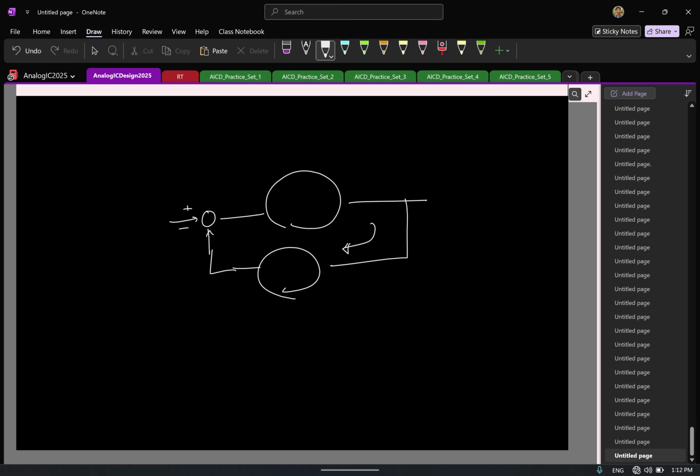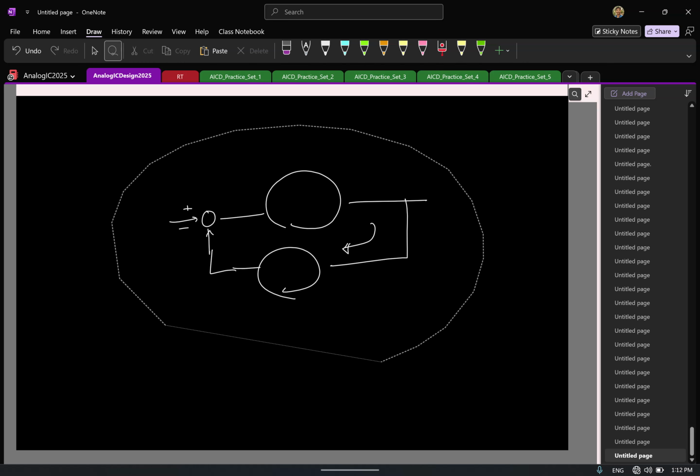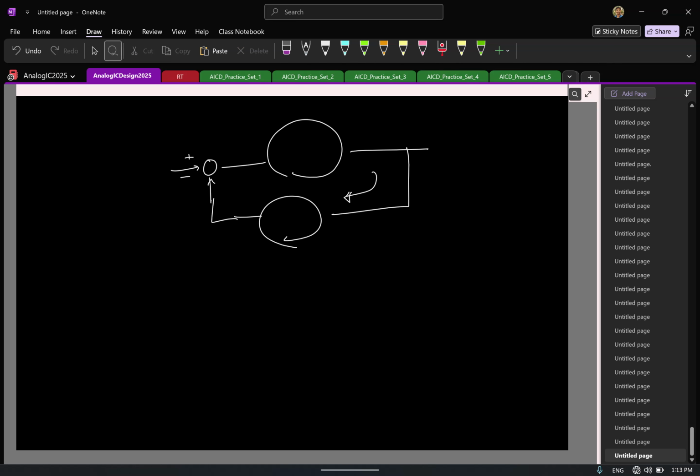Yeah, let's say you have a lot of delay in the negative feedback system. What can happen because of a lot of delay? Even fundamentally, forget about settling. The simple example I give is, let us say you want to take a bath in warm water during winter. You have two taps, one cold water, one hot water. You open both the taps and keep the bucket. So ideally what you do, you open both of them, you dip the hand in the bucket and check if the temperature is fine. Depending on that, you adjust it.